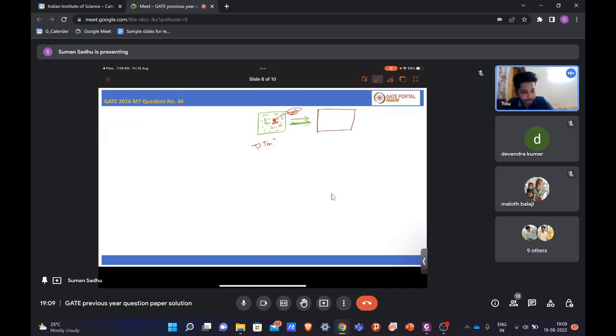Now if you are coming below the melting temperature, that is T less than Tm, what will happen? Let's assume somewhere that one small cluster is formed. Now if one more atom joins it, what will happen? If you are above Tm, this cluster will break down. But if you are below Tm, it will further stabilize this cluster. And so this smallest representative is basically called the critical nucleus. And you can even find this from the delta G versus r diagram that I will show.